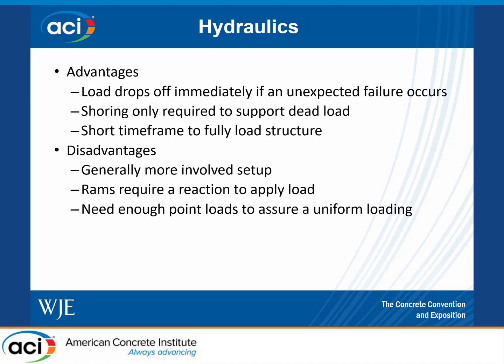For hydraulics, one of the main advantages is the load will drop off immediately if you have an unexpected failure, which is a big advantage. So that also will reduce the amount of shoring that you'll need, or the size of your shoring.